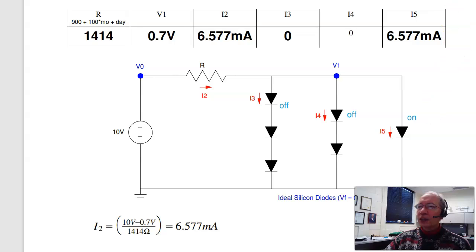Now with this circuit, one way to think about it is I've got diodes in parallel. Only one of these branches can be on. If the first branch is on, I've got 3 times 0.7, 2.1 volts. If I have 2.1 volts, that'll turn on the second branch and the third branch. So that doesn't work. If I turn on the first branch, I get 0.7 volts.